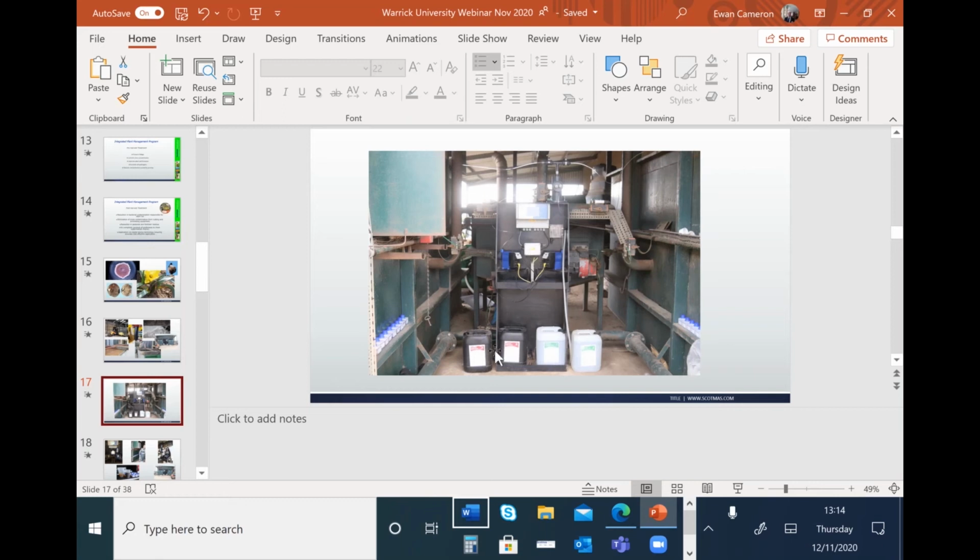So the acid and the chlorine dioxide mix in the chamber, which is up here, and we'll have a closer look at it in a minute. But this chamber here takes in these two chemicals. There's a resin-coated and etched glass, basically marble type balls, which are kept in here to increase the surface area. That gives us a complete reaction, and then we have two valves at the top here in this particular instance, because we were feeding onto two tanks, one on the left and one you can just see here on the right.